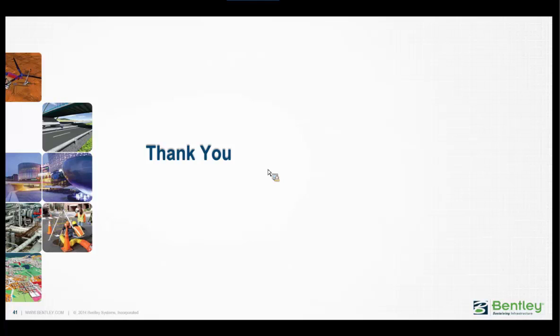Let's see. We have one more question here. Can you clarify the development of unity checks relative to allowable stress design versus LRFD design? I don't know if this is related to wind turbines or if this is just a more general question. Right. I don't understand what the question is, but I'll say that we have both. Whether you're doing LRFD checks or working stress design, we have both options. And the safety factors I mentioned earlier were basically the load factors for the LRFD code check, which is essentially what's required in Europe. And I think it's becoming the actual design code here in the US as well. It's basically based upon the ISO code. Right.